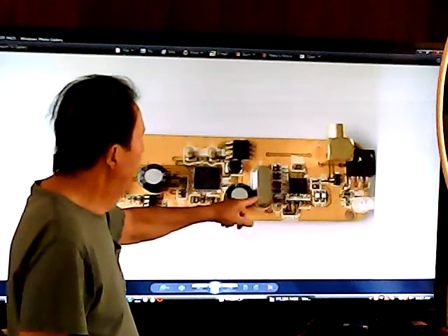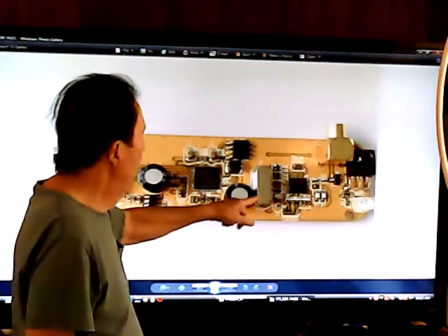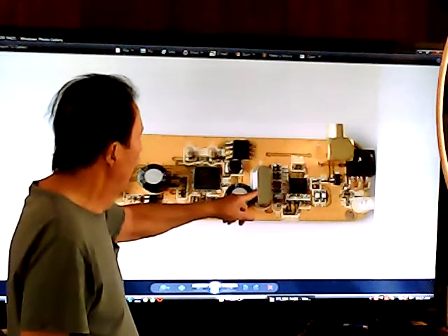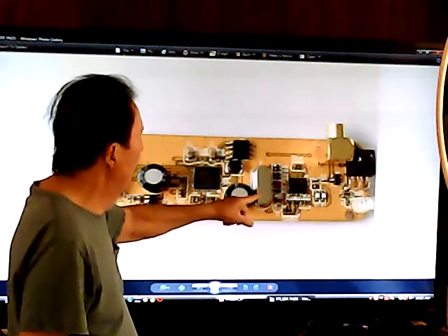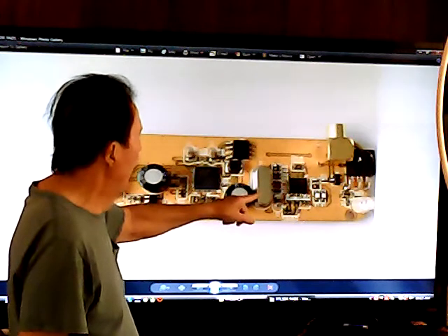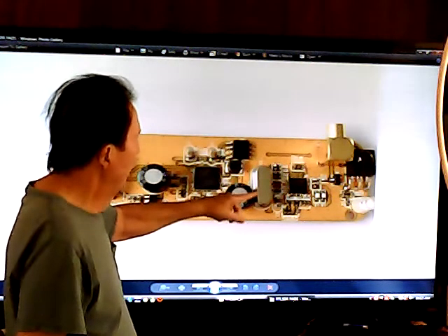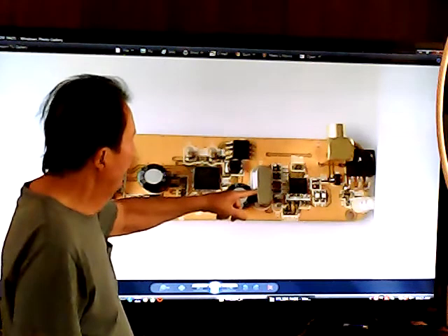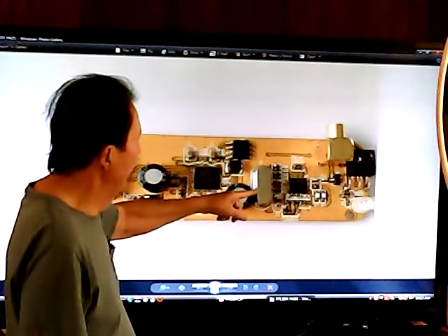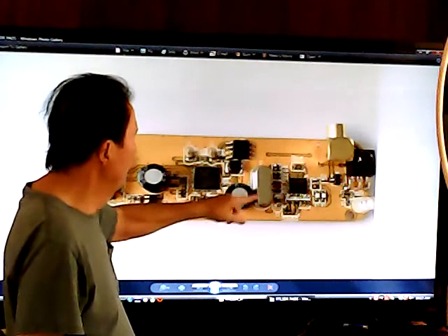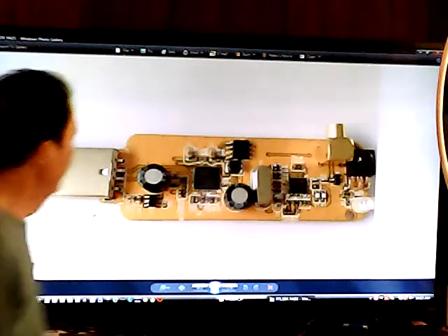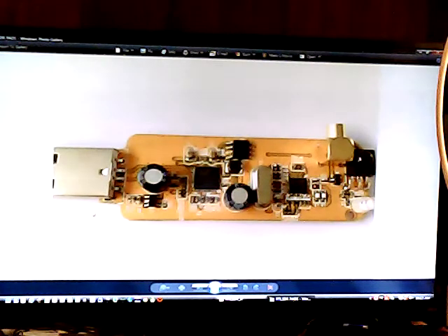The crystal doesn't really drift very much, but you have to use a correction frequency to get it directly back on frequency, which is used in HDSDR. There is a window you can pull up and set the frequency correction so that it's smack dab on frequency. It doesn't really drift enough to be noticeable in most instances.